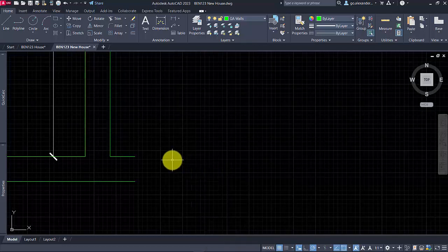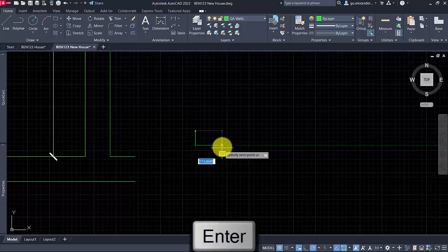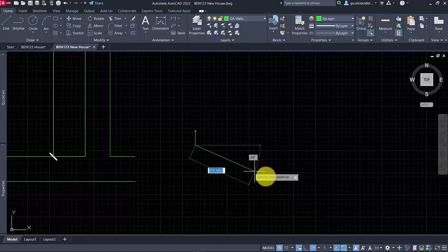So usually you have a break line in a scenario like this, and it is something of a, not quite a squiggly line, but a bit more like a heartbeat. So we're going to draw a polyline just at this stage. We're going to draw it down the way, a distance of 200mm, and then we're going to pick up an angle of 30 degrees here.